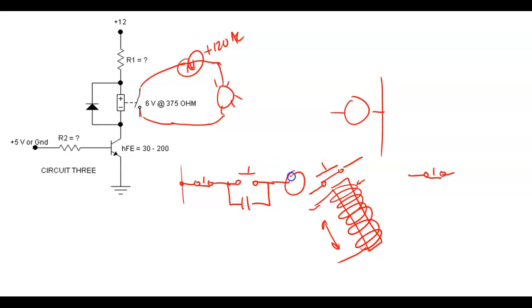And then we put our relay over here. So what we do is this right here would be, this would start everything, right? Usually when you hit an e-stop and pull it out, you still got to hit another button, right? And then this right here would be the e-stop. And then this right here would be main or something like that, and this would be the symbol of a contact being controlled by this relay. We just give them the same name.